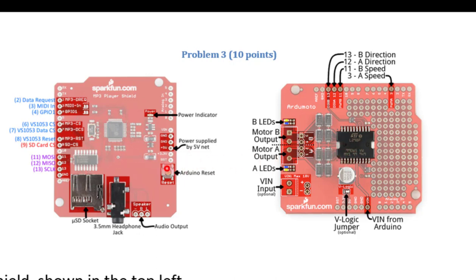So I've seen this before with students. This is a very common motor setup. And remember, pin 13 is the blinking LED, so sometimes people will be debugging their code and they'll say, well, when I sense something, I'll have the LED turn on. And the LED turns on, but maybe their motor is turning on too. So this is a difficult one to fix if you're actually stacking the boards.